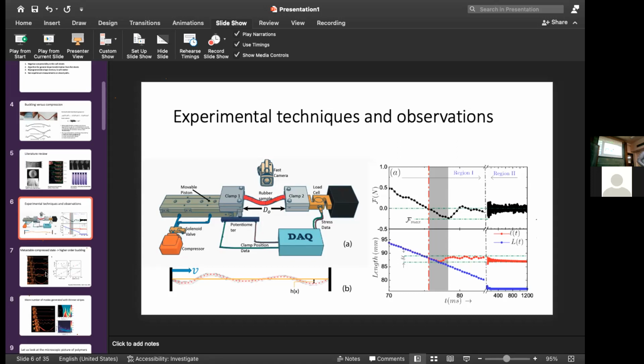And the second one is, can you talk a bit about your measurement technique, and how do you measure the force? Okay. So this is a simple load cell, but it's basically a Wheatstone bridge. We have 4 resistances arranged in the form of a Wheatstone bridge, and as soon as there is a slight displacement on one axis, there will be some millivolt change in the resistance that I measure at the ends, and that is accurate enough for me to measure extremely small forces.